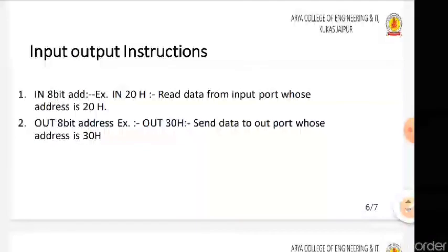Input output instruction. There are two input output instructions most commonly used. IN 8-bit address. It can be any 8-bit address here. For example, IN 20H. Here 20H is the 8-bit address of input port from where we read the data, the input port whose address is 20H.